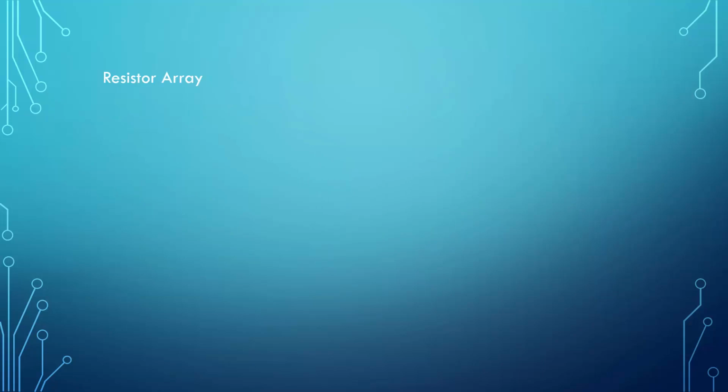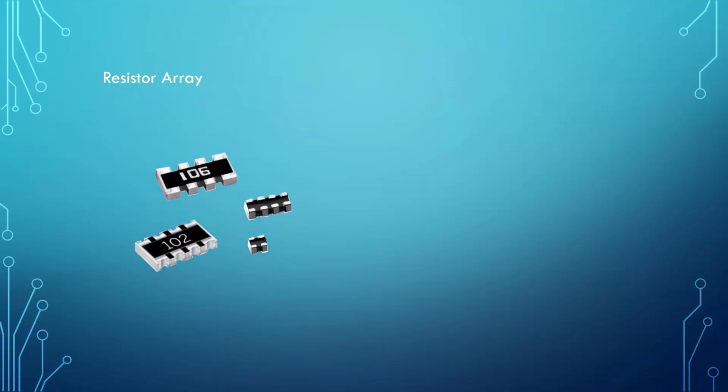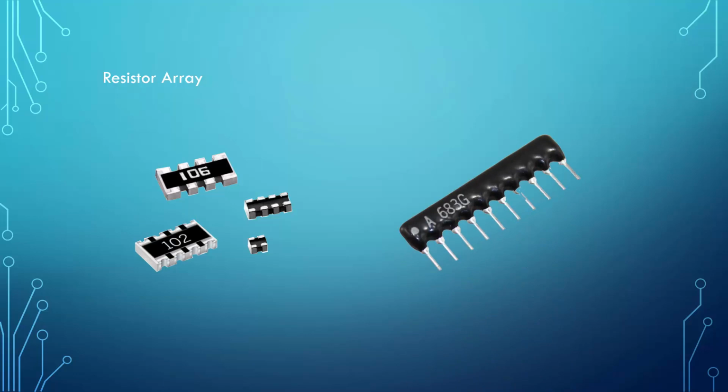A resistor array or resistor network is a single package that contains two or more resistors. The package will include multiple leads by which the network can be made part of a larger circuit. The main advantage of a resistor network is space and time. When using the same value resistor multiple times, as in pull-up resistors or a microprocessor bus, placing one component that has say 8 resistors in it with no space between them saves more space. We talked about pull-up and pull-down resistors in a previous part.